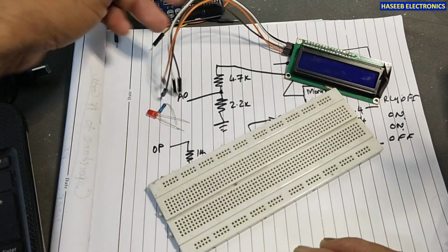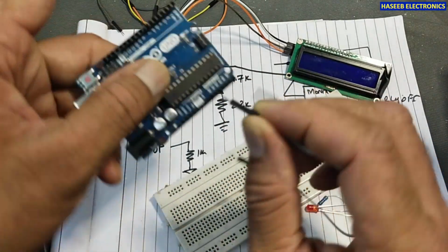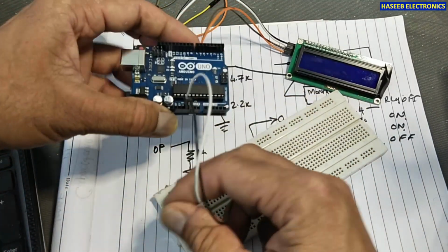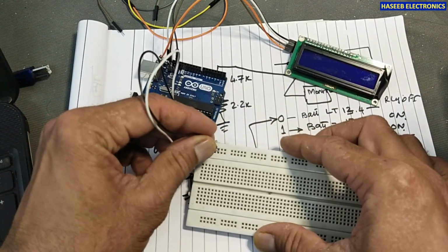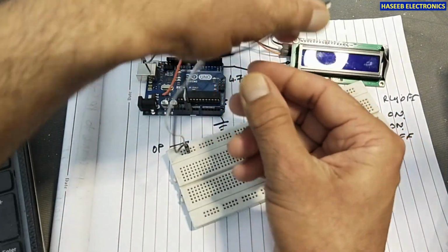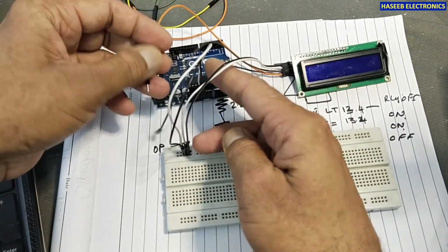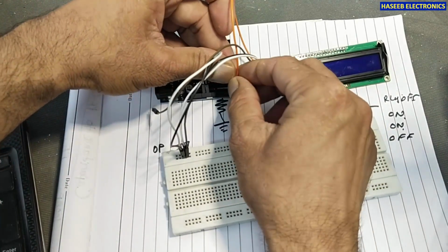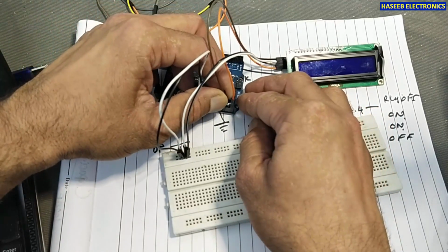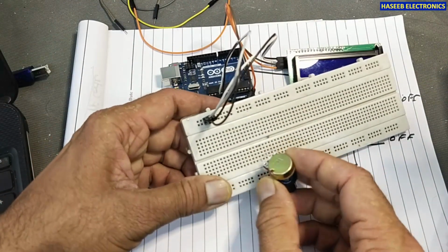So let's connect. I will take positive and ground volt from this Arduino power supply, that is ground and positive 5 volt. I will inject it to this ground and positive rail, and we will connect the ground and the positive voltage of this LCD, and we will connect the SCL and SDA pins. SCL will come to pin A5, analog number 5, and the SDA data pin will come to A4. That's good. And I will use this potentiometer here